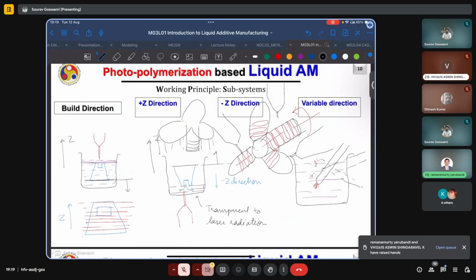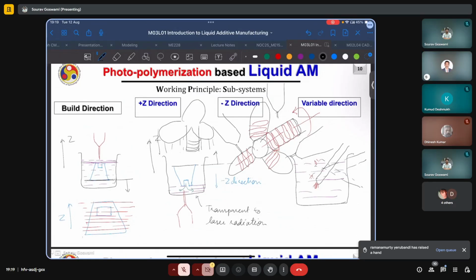Okay, that's complicated. It's not a straightforward answer. There can be, yes, of course, because locally the dynamics of heat transfer and the microstructural growth will vary. So it is expected that there will be a change in strength, but then again, strength, the way we characterize it, is a bulk property. What will be the bulk value? Will it be very different from a part which is printed along just one fixed direction?